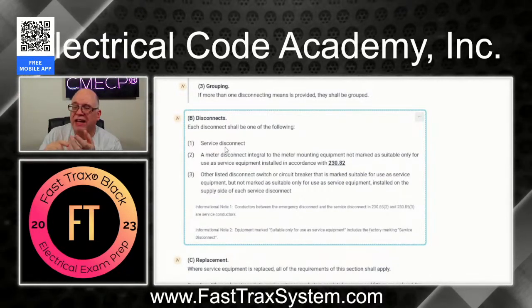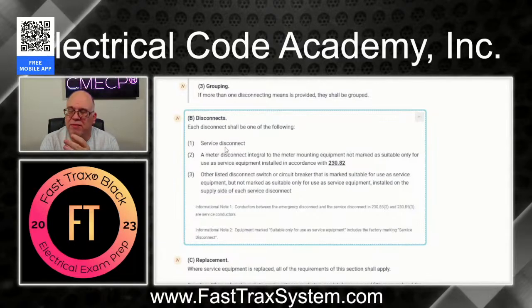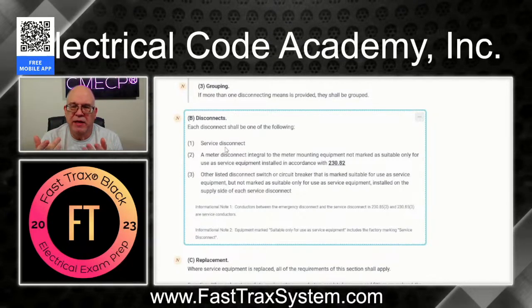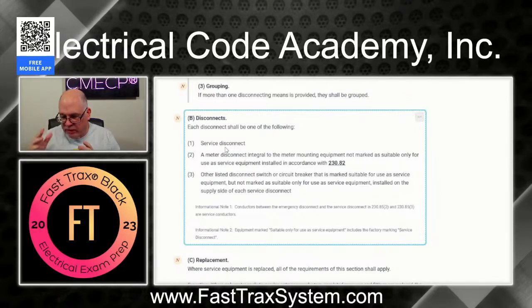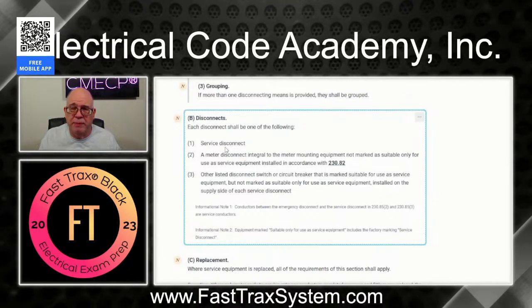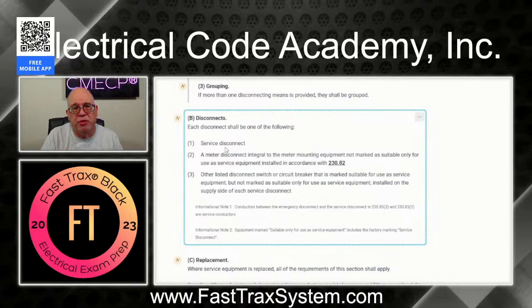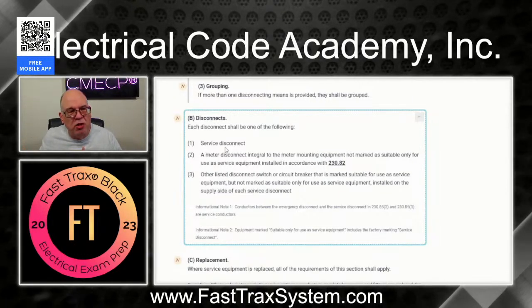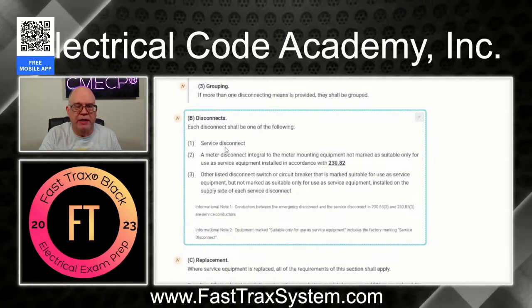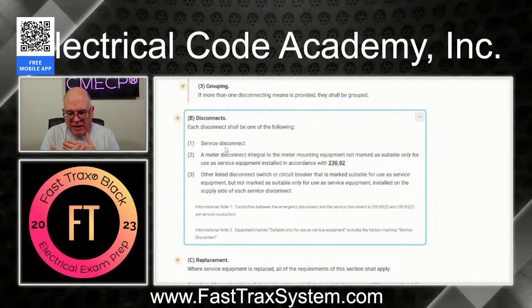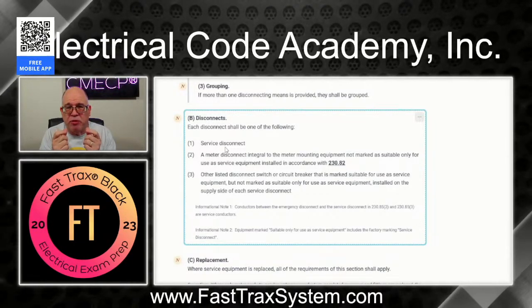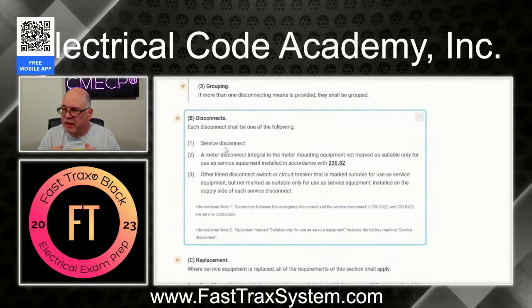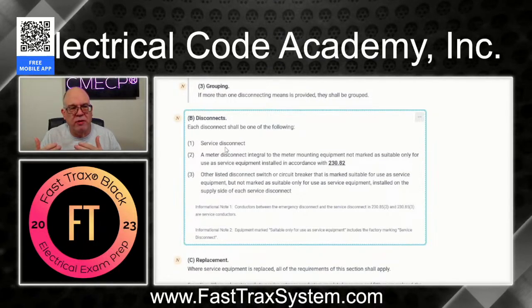Now, is that going to add some additional cost to the install? Well, of course it is. But again, I'm going to get rid of a lot of problems that people have with the exterior NEMA 3R, where you have to worry about how you get those cables into it. And if it's installed on the side of a building and it's got that 1/4 inch gap in 312.2, then how do I transition and meet the code?